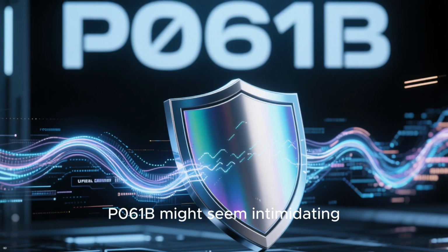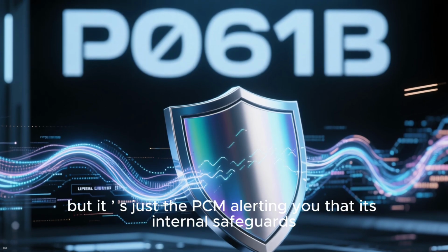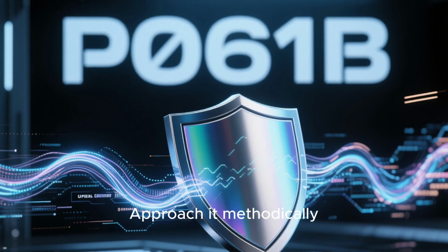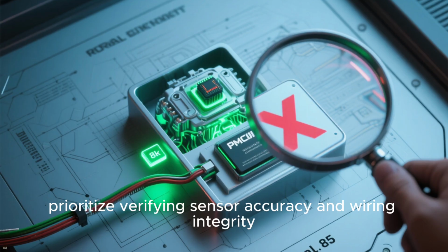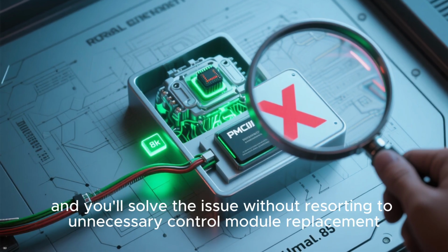P061B might seem intimidating, but it is just a PCM alerting you that its internal safeguards have been triggered by inconsistent data. Approach it methodically, prioritize verifying sensor accuracy and wiring integrity, and you'll solve the issue without resorting to unnecessary control module replacement.